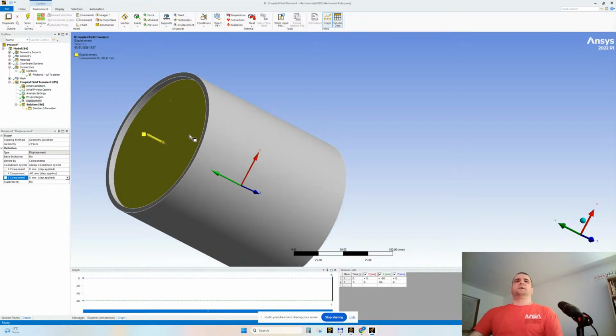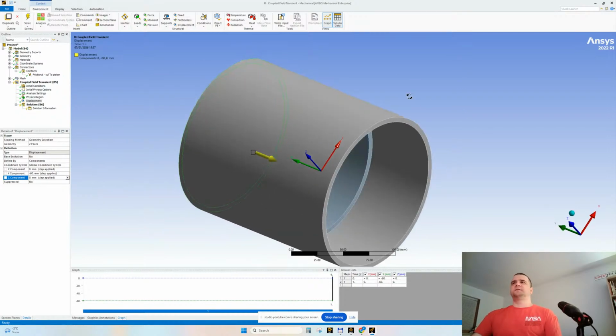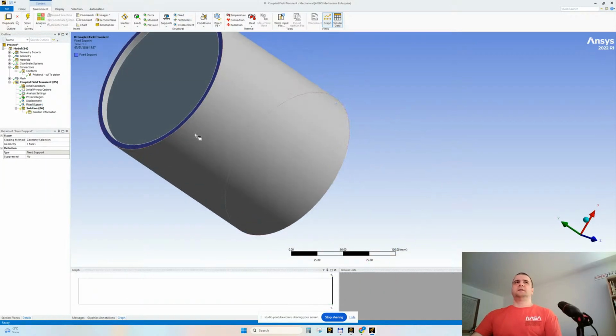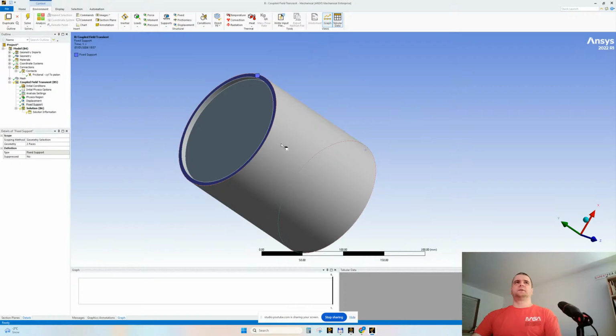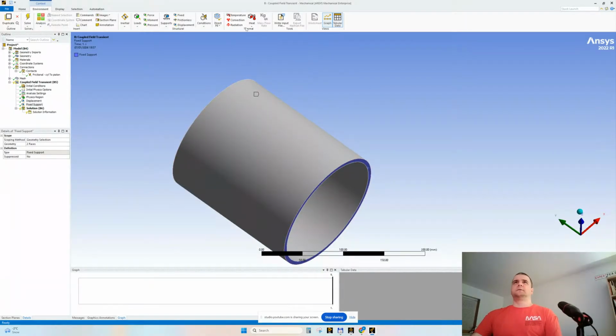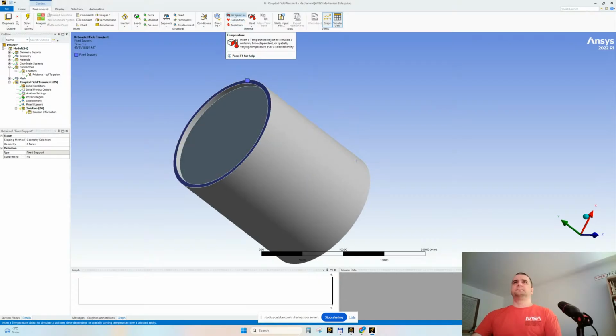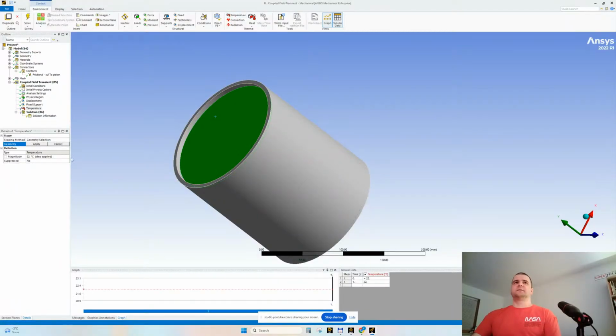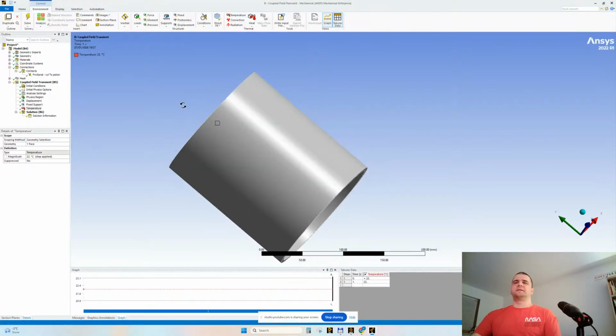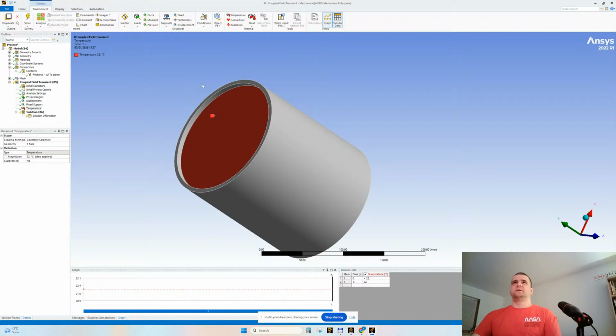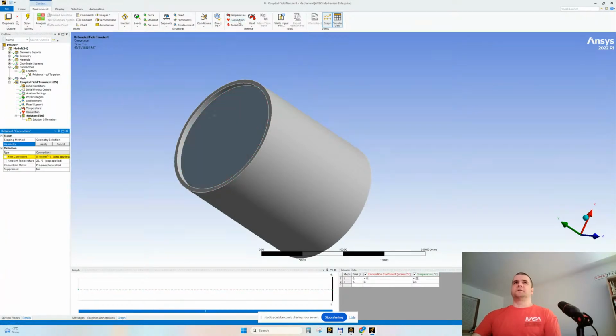What else do we need to apply? Another fixation. Control pressed, fixed on the cylinder, and let's assign, just as a reference, a reference temperature 22. I think it's kind of mandatory in these simulations, and an overall convection. Can we look just for fun? It's called film coefficient, yes?